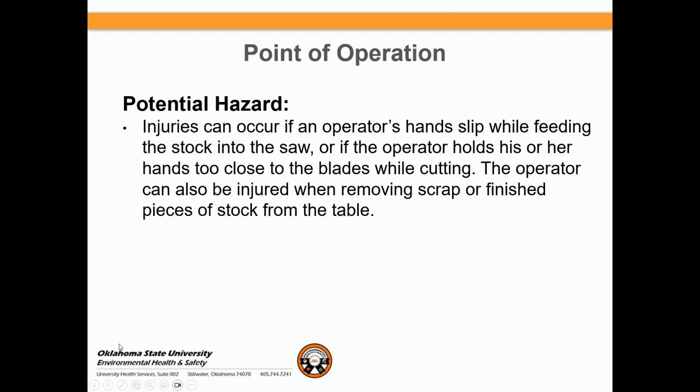The point of hazard, or what they call the point of operation, is exactly where the material is going to be cut. Injuries can occur if an operator's hands slip while feeding the stock into the saw blade, or if the operator holds his or her hands too close to the blade while cutting. The operator also can be injured removing scrap or finished pieces of stock from the table.